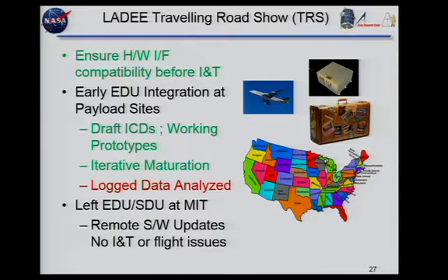Sorry, it wasn't a missed command, it was a missed telemetry message. And sometimes they would come out quicker than others, like the printf type event could come out rather quickly. So we were getting a message too quickly. There's 2 buffers, so it was a buffer swap issue, but by the time we swapped buffers, we'd missed a message. The problem was in the driver, and the flow control wasn't in the right place to hold off between data that was coming down. So we had to get the scope out and look at all the messages, and after a couple days we could apply the fix, but it was a little bit stressful.